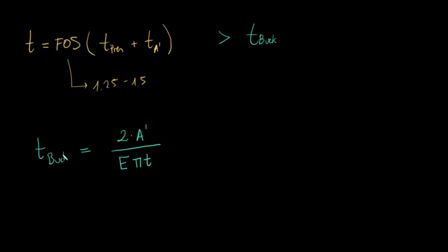Fleeman also talks about the minimum gauge for manufacturing, which is the minimum thickness required for manufacturing processes like drilling holes. He suggests around 1.5 millimeters as the minimum. It's strange that these numbers would give you values around 1.5 millimeters, but just in case, you can't go much lower than this if you have to machine and drill and everything.